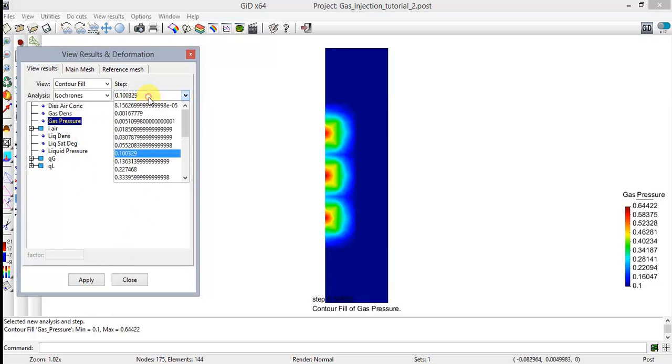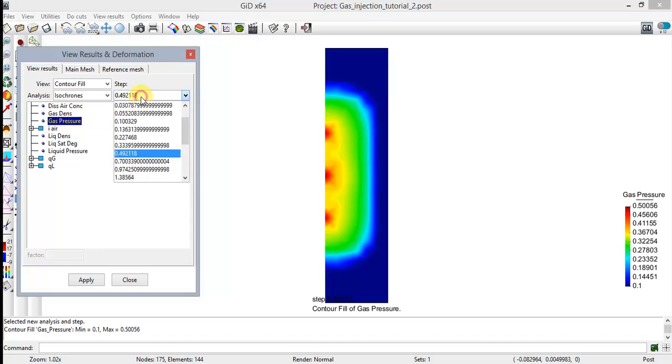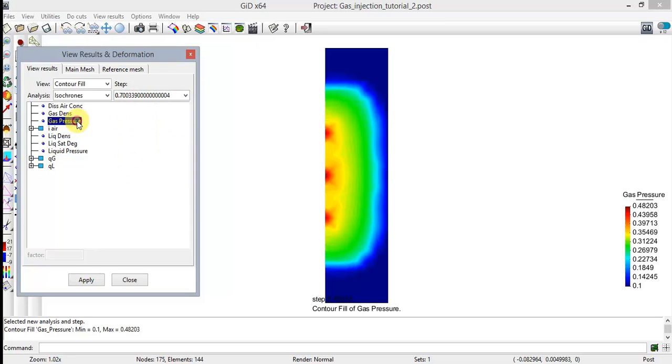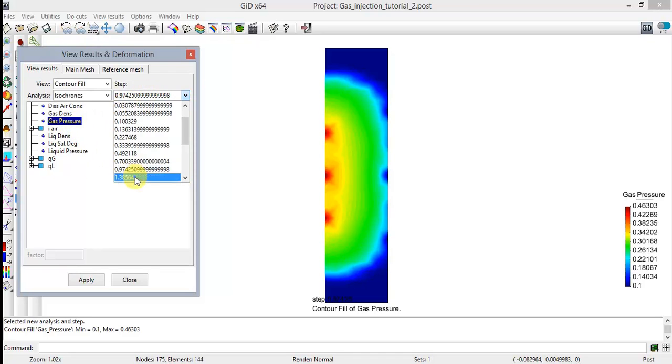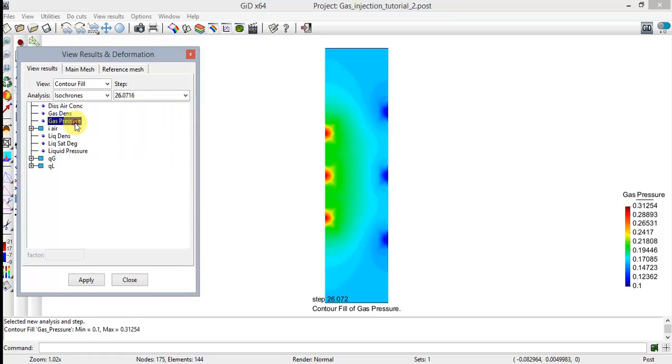At the beginning, the porous medium is saturated, which means that the degree of saturation is equal to 1. It will be observed that due to the gas injection, the medium becomes unsaturated. The water is displaced by the gas or air in a progressive way, and at the end time of the test, 240 hours, the degree of saturation has been reduced to 0.85.